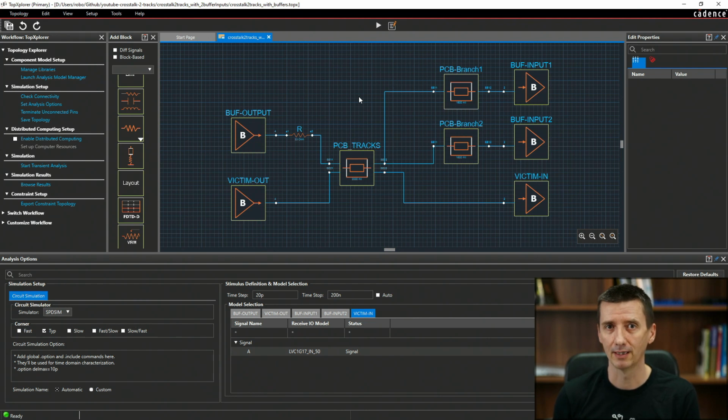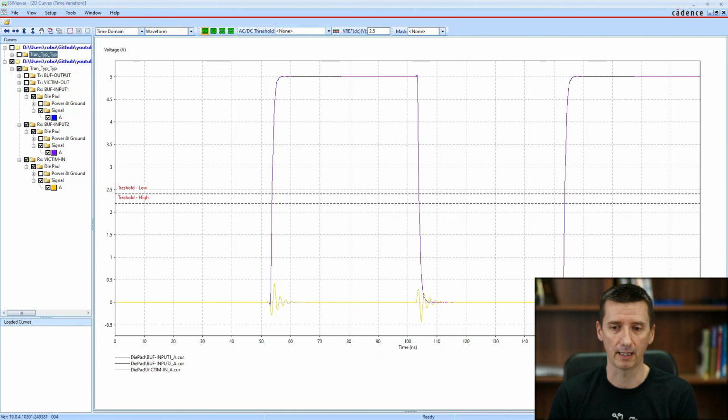But as you can see, it still can work very well. For example, if the impedance of the output buffer is very low, you can add a series termination resistor. Usually they are 22 ohm or 33 ohm series termination resistors, and this can help a lot. And not putting any special termination on the input of these input buffers, it's nothing really wrong, as I said, and as you can see, we still can get really good high quality signal.